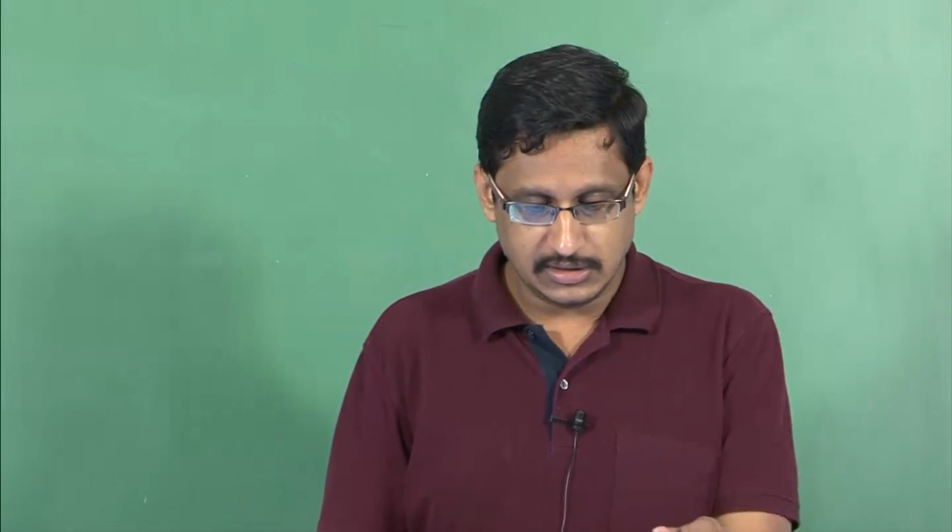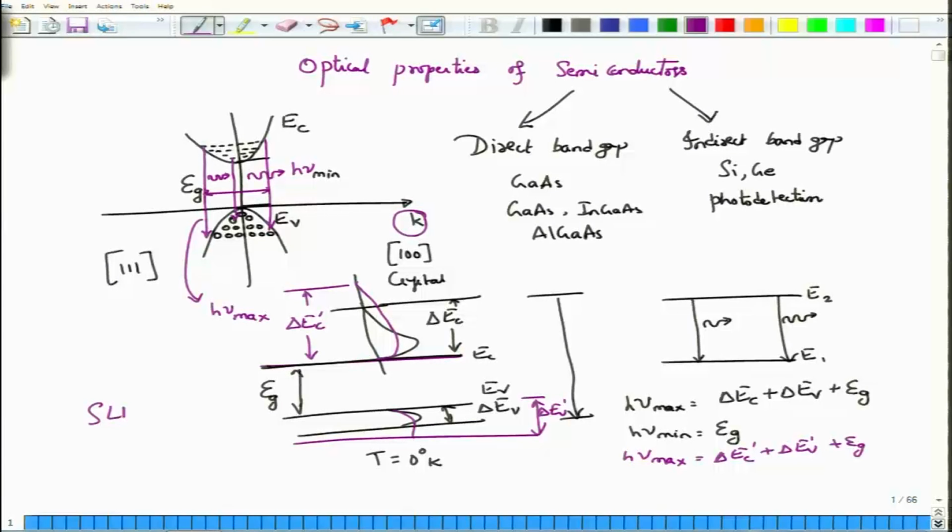Okay. So in most semiconductor laser diodes, temperature must be maintained very accurately, with as much accuracy as possible. Temperature must be maintained at a given value. Any increase in the temperature causes the line width to spread, and increased line width is absolutely bad for communication purposes. Okay. So this is essentially the idea.